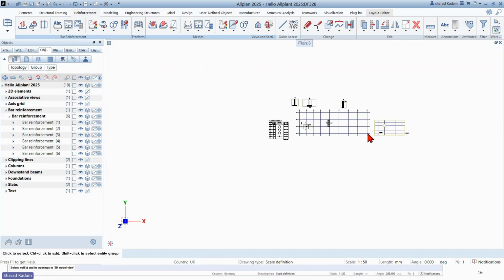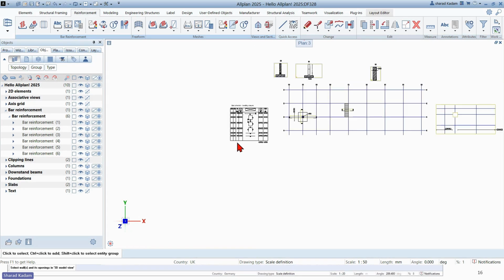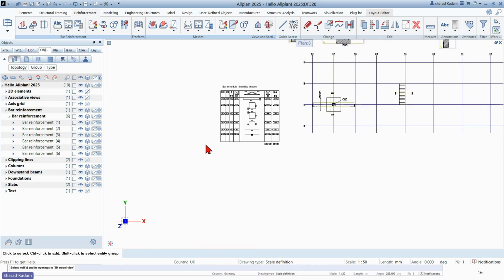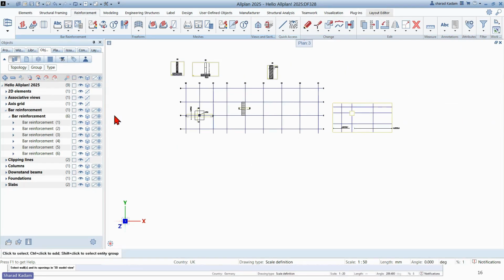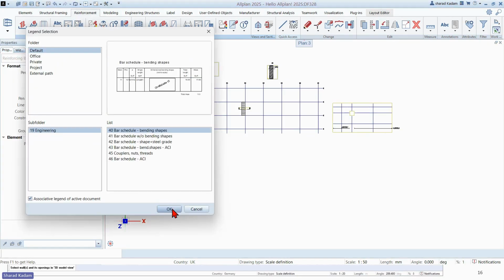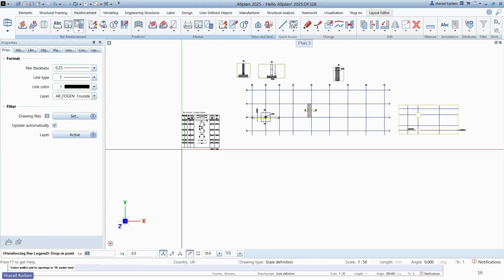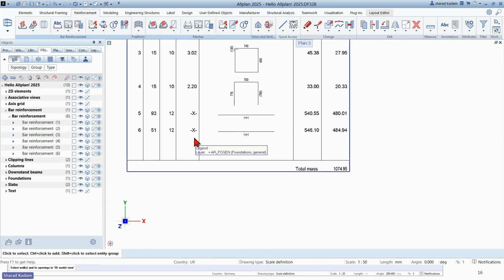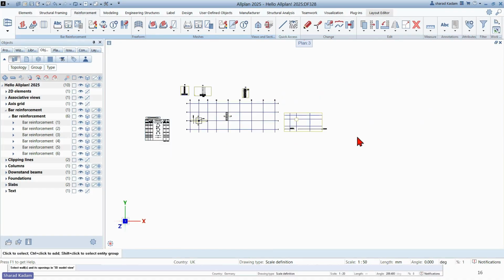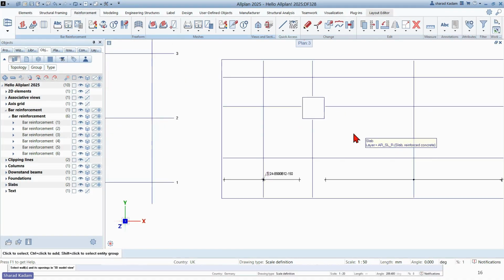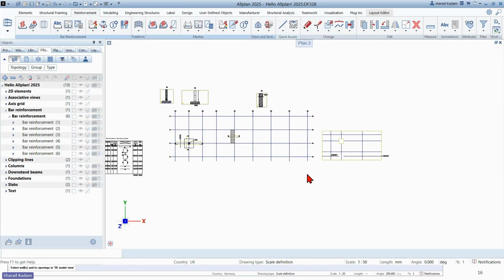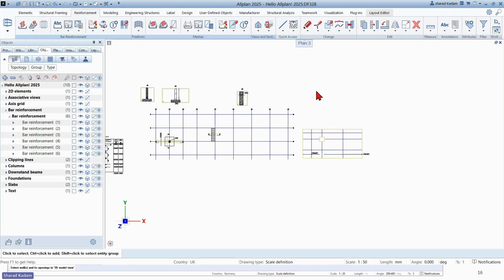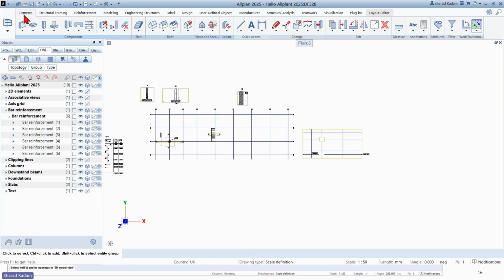And side by side, we can see that it is automatically updated over here. So whatever rebars we are adding, we will be getting the bar bending schedule in real time. So if I just add my legends again, so here I'm putting the rebar list again. So it has added this rebar as well. So whatever was there from this part, it has added it. So that's about the normal method. And we will be seeing some more tools.